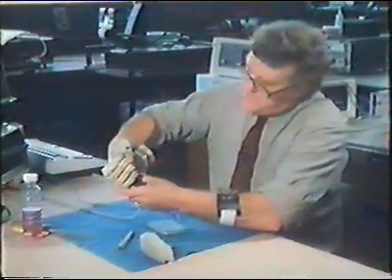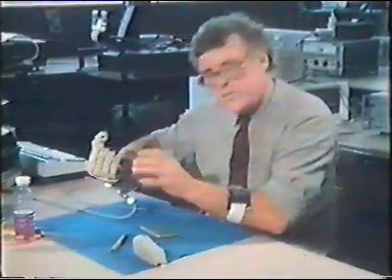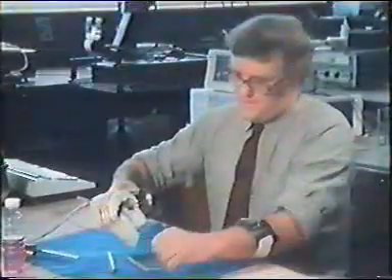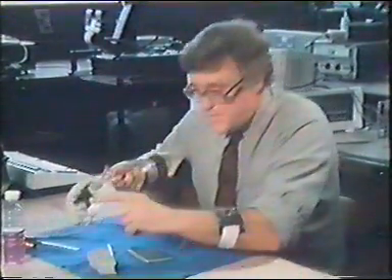There's an even more interesting sensor on this, and that's here in the thumb, and all it is is a microphone underneath this piece of Velcro. And when I want to pinch something in between the fingers, I can pick up this piece of sponge like that, and as I pull this piece of sponge out, or attempt to, the sound is transmitted from this sensor here into the computer. When it hears the sound, it automatically tenses up the hand to stop me from withdrawing this piece of sponge. In other words, it's a complete feedback mechanism. No signal from my hand is affecting it. And I can simply open the fingers and let it drop. There's another sensor here on top.